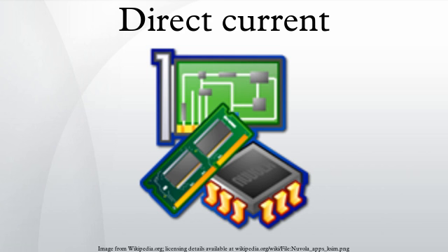In a telecommunications system operating at 48V DC, it is generally more efficient to step voltage down to 12V to 24V DC with a DC-DC converter and power equipment loads directly at their native DC input voltages versus operating a 48V DC to 120V AC inverter to provide power to equipment.